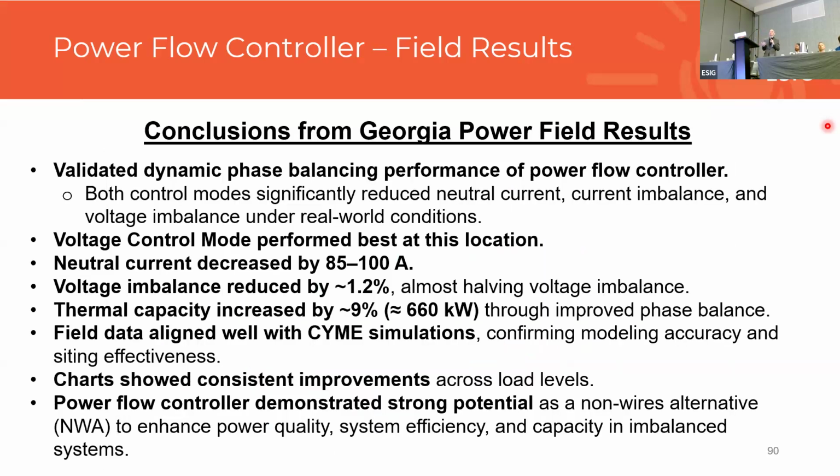And the conclusions of the pilot study: it validated that it was able to dynamically balance the system. Both control modes significantly reduce your neutral currents, current imbalance, and voltage imbalance under real world conditions. Voltage control mode performed best at this location. It's not necessarily true that voltage control mode will always perform best, but it was interesting to see that they performed fairly neck and neck across those.